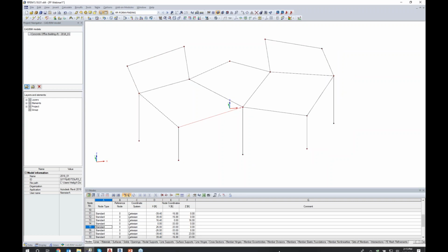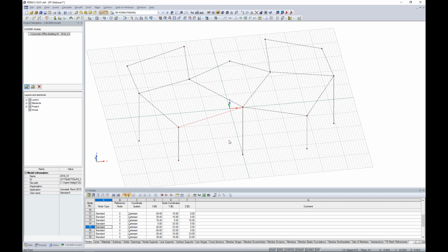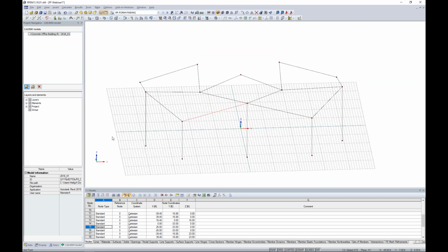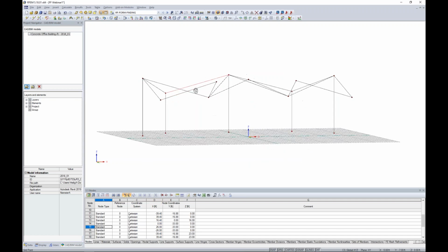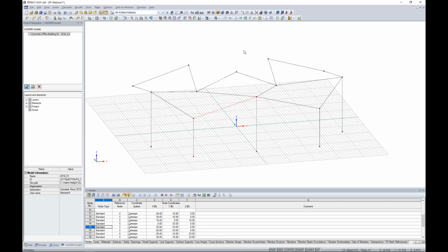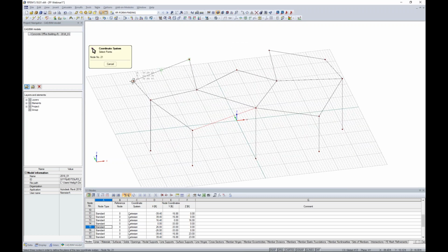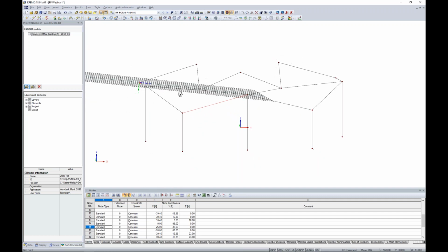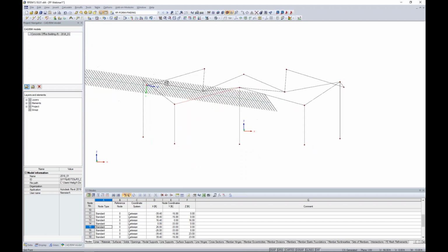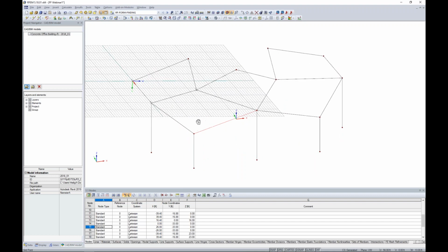Well, how I can do this is to turn back on my grid down at the bottom, and we don't want to use these global X, Y, and Z coordinates because we have some pretty odd geometries here. Well, we have a nice feature in the program up here in the top where we can actually define our own work plane by clicking on 3 grid points. So how I can do this is to click this option once. I click 3 times to define my grid, and then you'll notice that my drawing grid is automatically placed at the incline that I've specified with those 3 points.